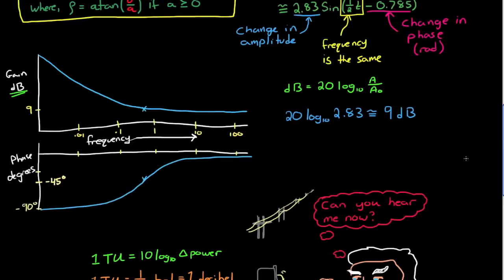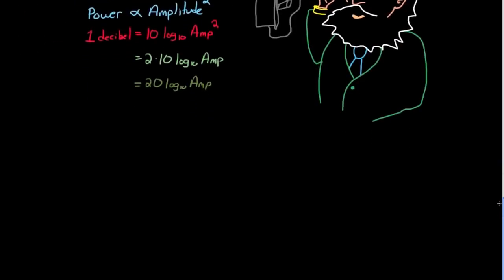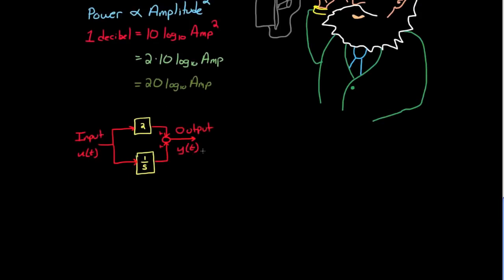And with the exception of being time-consuming, for this simple example, solving the response to the sine wave input was relatively straightforward. Well, except for having to remember that crazy trigonometric identity from earlier. There is a way of solving this without having to remember those identities and still produce the same relationship with frequency, and that's by referring to the system's transfer function. If we take the Laplace transform of the system above, the gain of 2 stays at 2, and the integral becomes 1 over s. Now writing the transfer function for a system like this can be done.